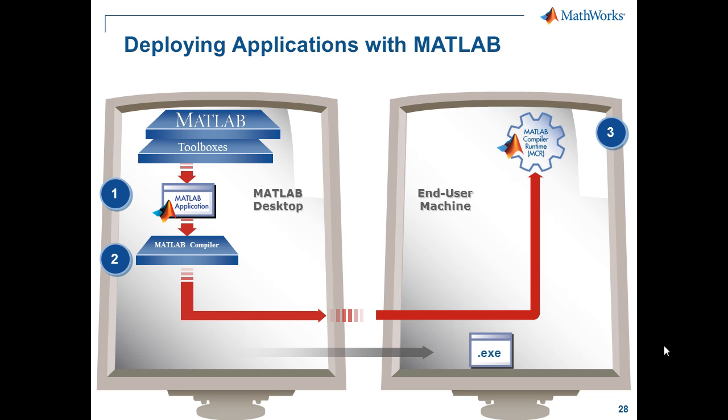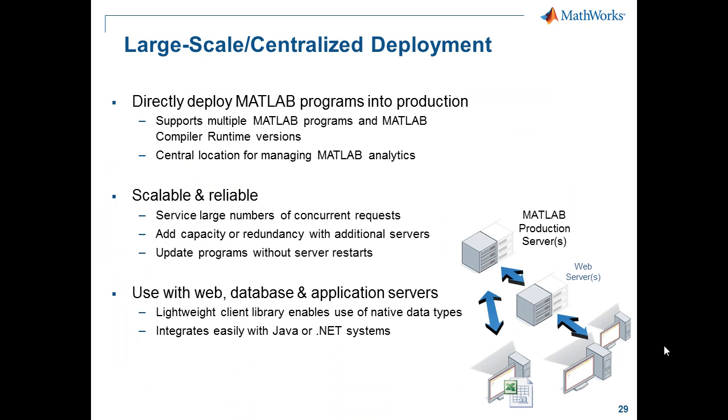So the MCR is a one-time install, and with the MATLAB Compiler, it gives you the license to distribute the MCR to as many people as you like, and also distribute the compiled applications and shared libraries to your end users as many times as you like as well. This approach works very well for distributing MATLAB applications and MATLAB functions that you write to a large number of people.